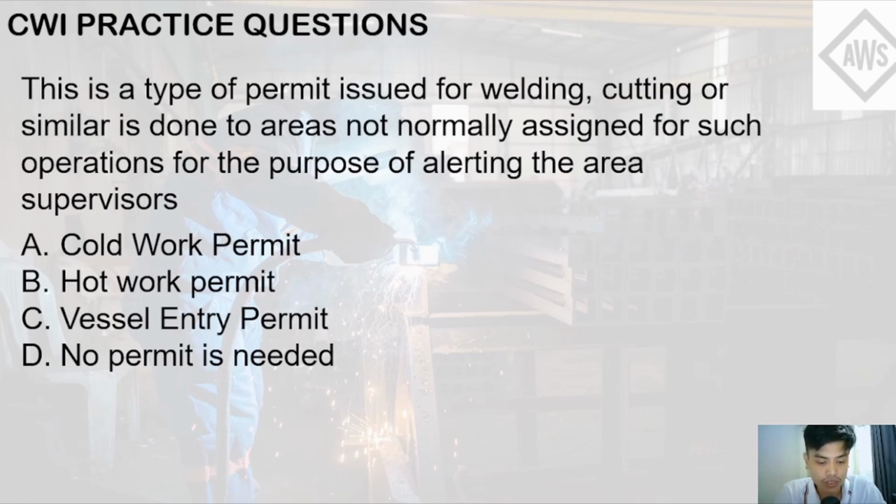For refineries and plants that are normally not designed for any welding or hot work activity, a hot work permit is needed to alert the area supervisor of any activities that will generate heat, which will be a hazard to the plant because it might ignite the fumes.